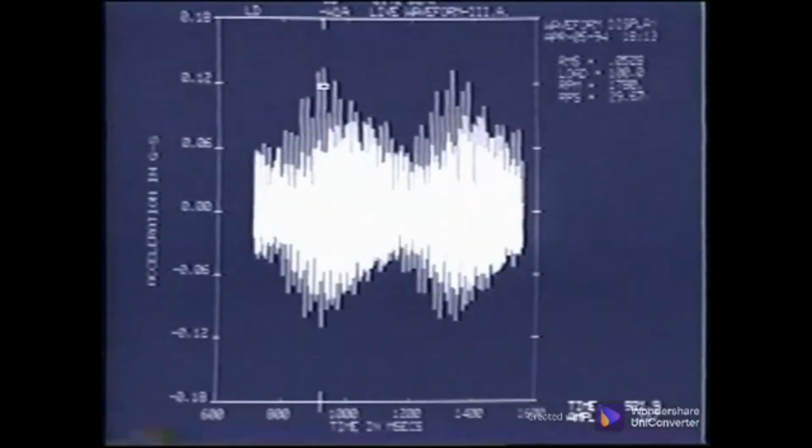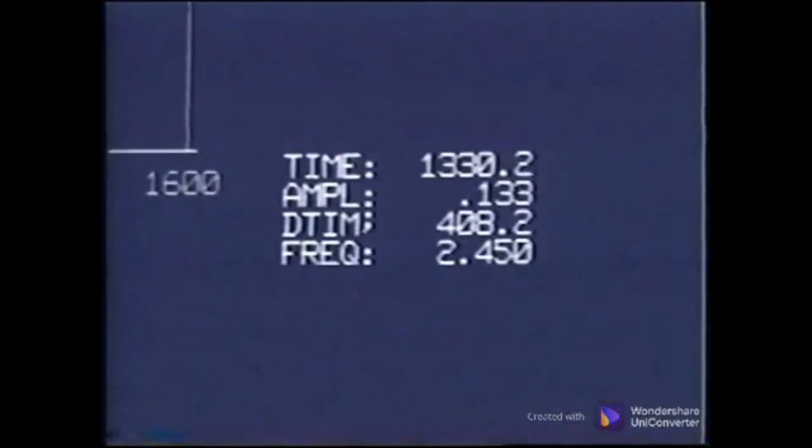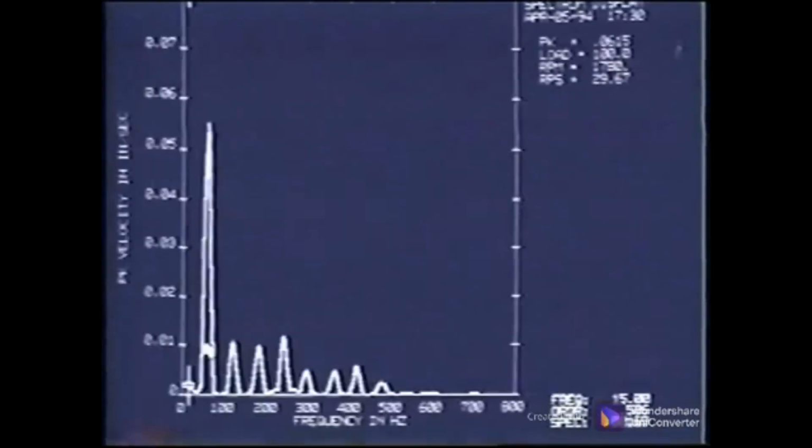Expanding the 2-second waveform of the 200 hertz data allows us to check the time differential between the low-frequency events. We see that the time for one event is 0.4 seconds. This time is equal to a frequency of about 2.5 hertz. The 3000 hertz spectrum with 400 lines of resolution has a minimum frequency of 15 hertz. This event cannot be seen in the spectrum at its fundamental frequency. It has been left out of the spectral and waveform data.